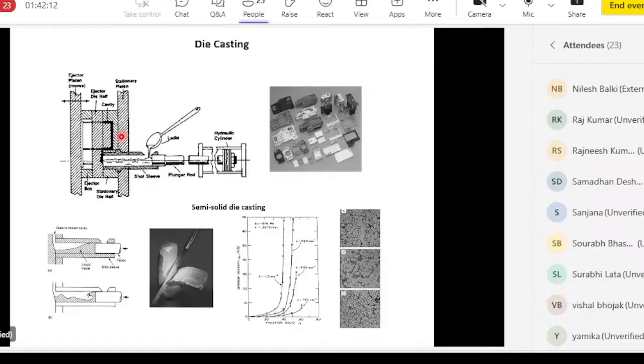And as you know, die casting is mostly used for making thin-walled components, because they will be difficult to produce by gravity casting in a permanent mold. Gravity may not give enough pressure to fill small sections. But with die casting, you can fill thin sections to make thin-walled items. So that's a very commonly used process for the automotive industry.